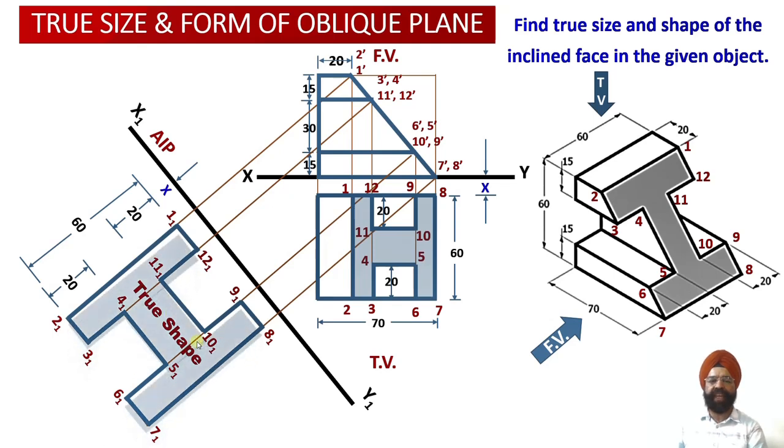And now we can carry out the shading of this portion, and we can say that this is the auxiliary plan that we have developed onto the auxiliary inclined plane. So this is the procedure for obtaining the true shape of the inclined section surface which is lying on the top of the solid, which has been cut by an auxiliary inclined plane, right?